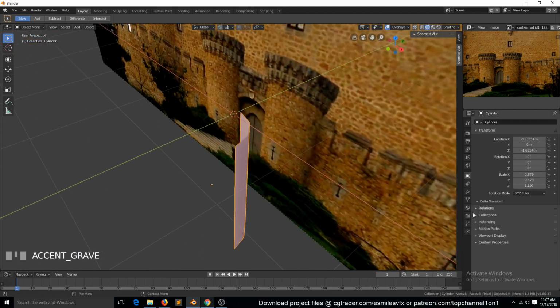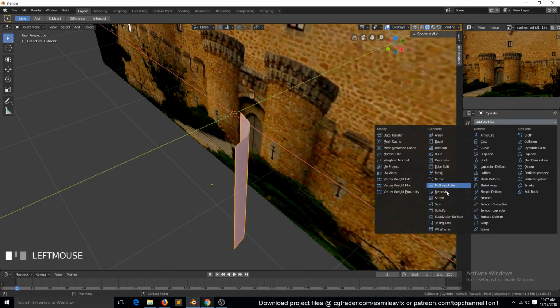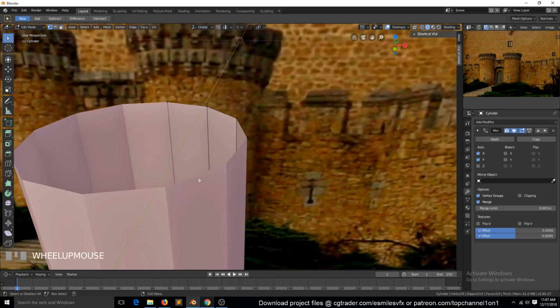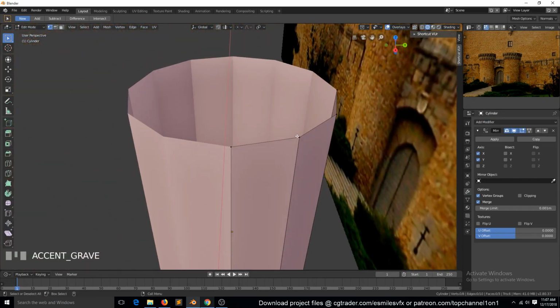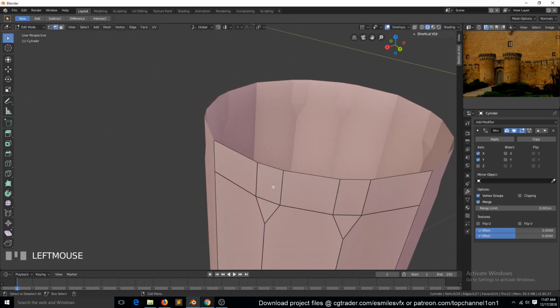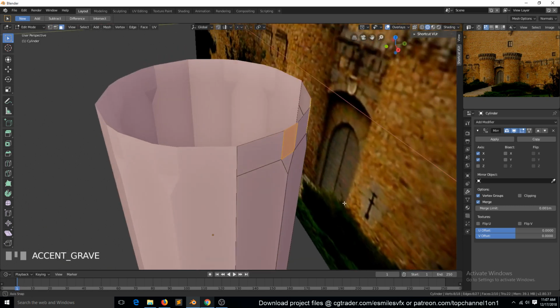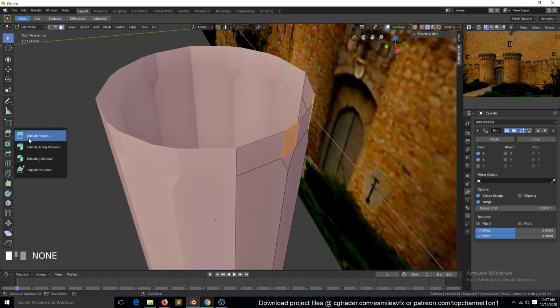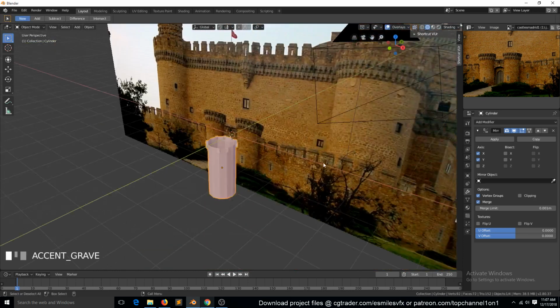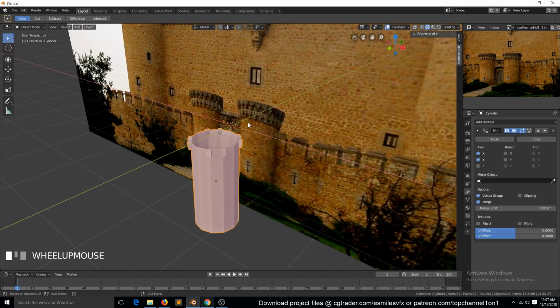So what I was going to do was go to edit mode, delete all of this, and just remain with one section like that, and then use the mirror modifier to bring all the other parts back, and then I would just start adding more details, maybe like beveling this, then extrude along normals for this until I got the shape that you see those rings are created.